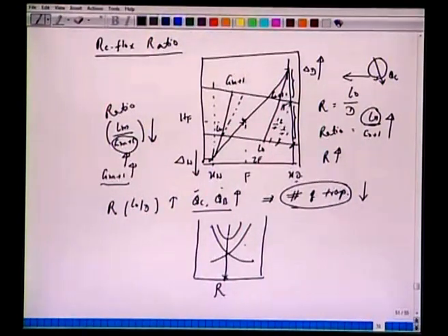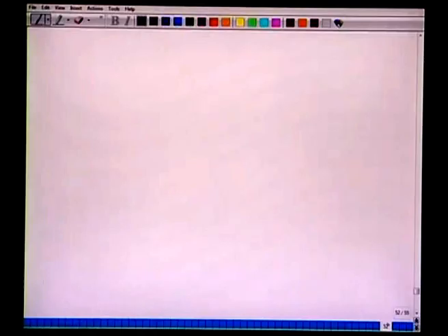All right. Of course, we have not defined here what our maximum limit and minimum limit are. But looking at this curve, the locus of del D going up and del W going down, you can think that under very extreme conditions, when this del D is very large, all these tie lines will become vertical. So, if you plot this for very large reflux ratios, which we will call infinite reflux ratio.